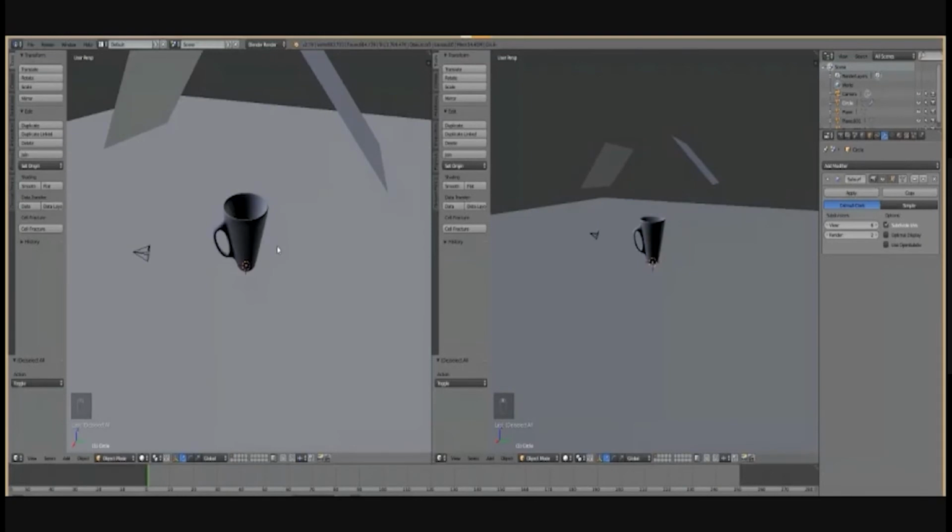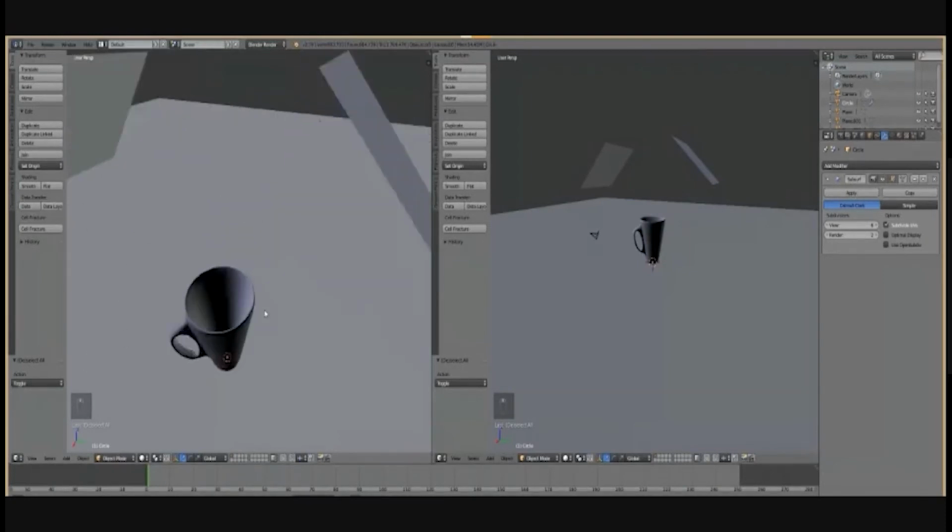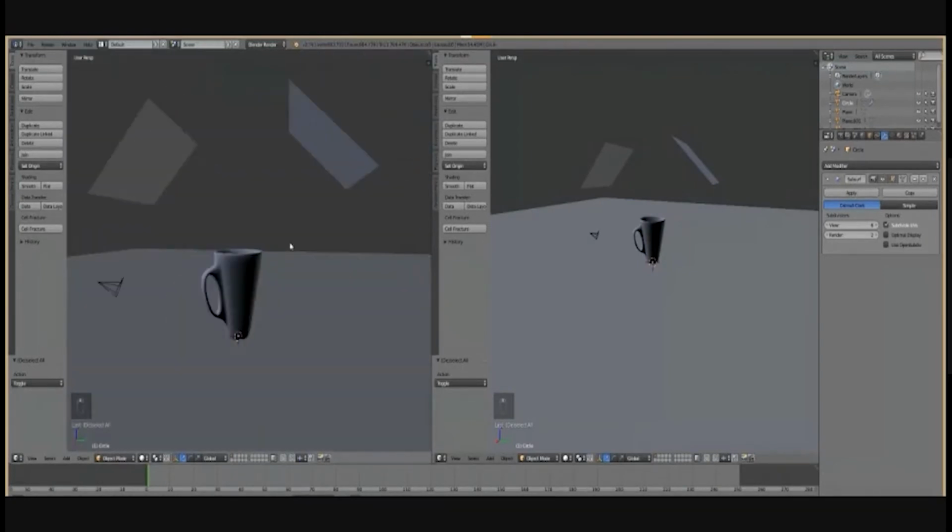In order to do that, first on the top, you will see a button called Blender Render. Click on that and change it to Cycles Render. This is essentially a render engine. It's Blender Render by default, and we're going to change it to Cycles Render.